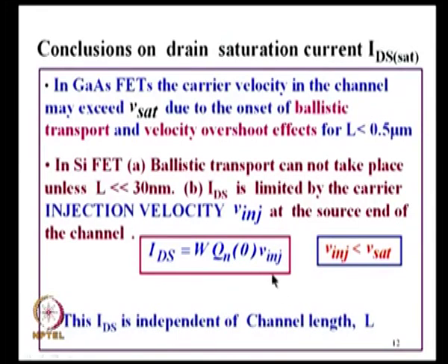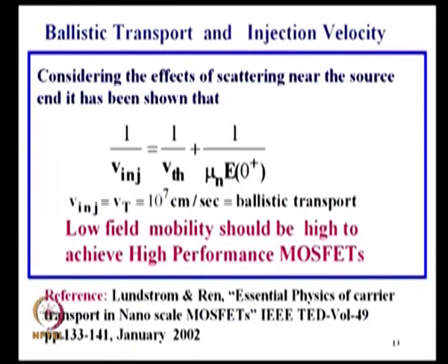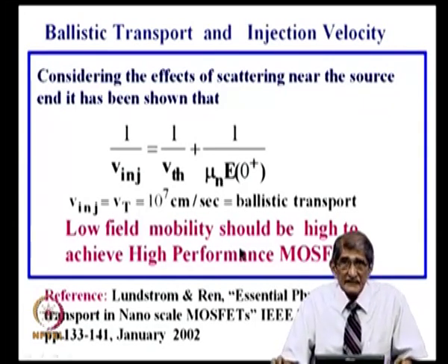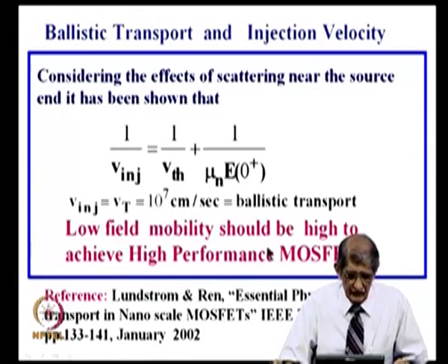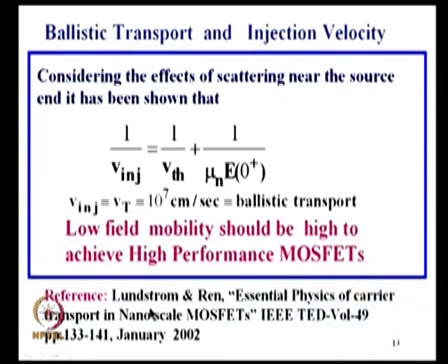But this injection velocity does not depend upon channel length, it would depend upon the conditions at the source end. Let us see what it is. I will not derive it, but I will just show that, because the deriving is a bit of an involved thing. There is a detailed paper written by Lundstrom and Ren on the physics of carrier transport in nanoscale MOSFETs, published in January 2002, in which what they have said is,